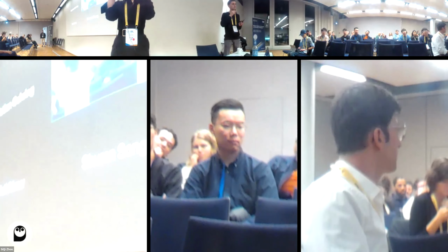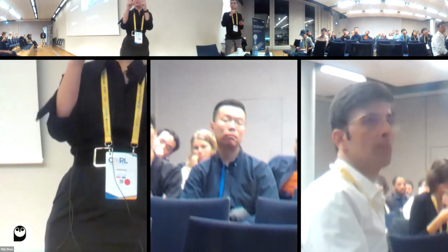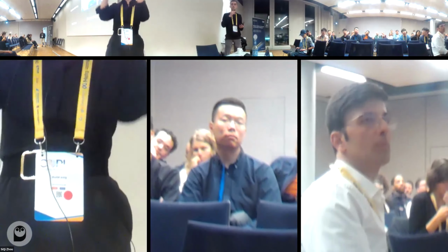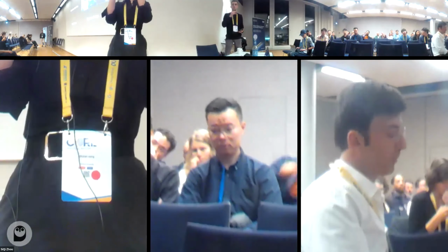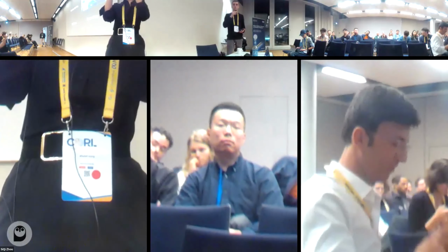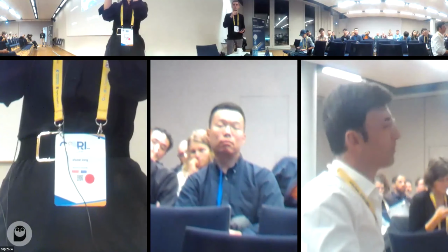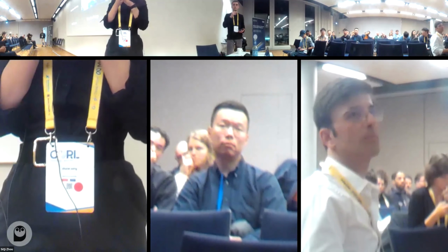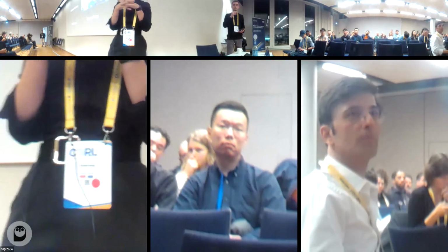You mean the deformation, right? When we read the paper, we make the point that you can estimate the deformation from the finger, or estimate the force from the deformation. But it's kind of hard because the material that we use is stiff. It doesn't deform that much. And when we change it to a very soft material, it cannot pick up very heavy objects because it bends. So that's a problem.